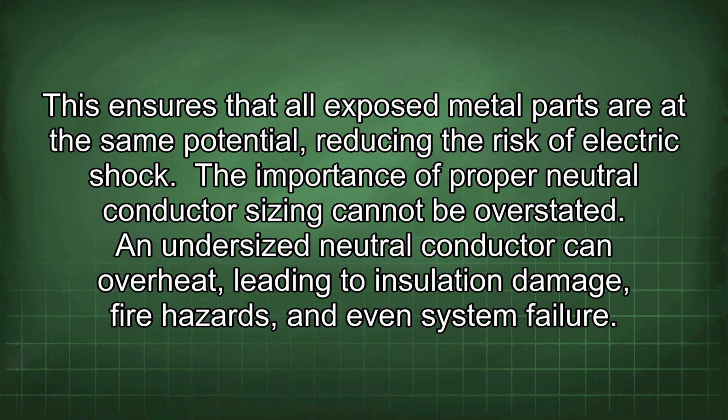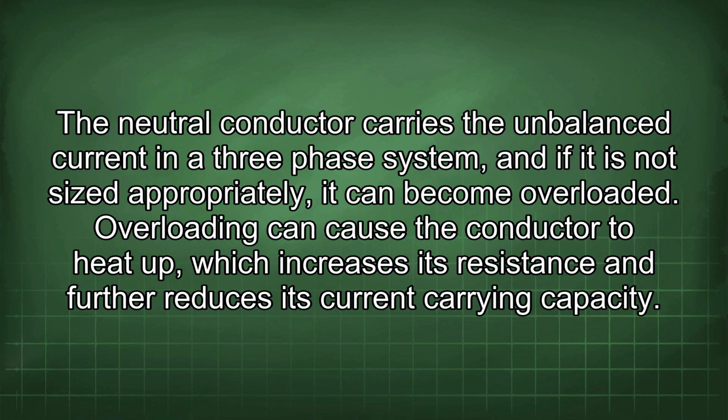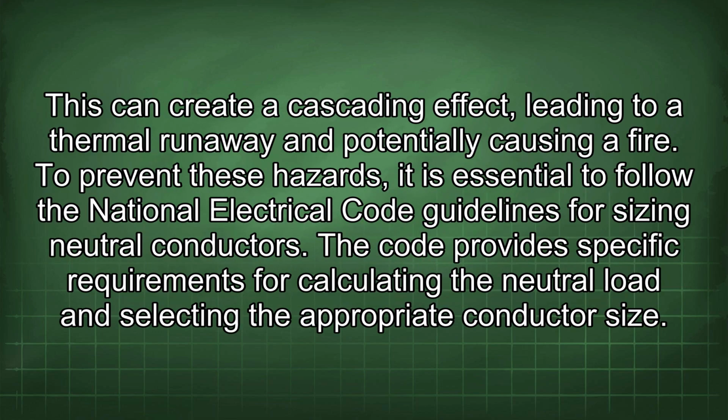The importance of proper neutral conductor sizing cannot be overstated. An undersized neutral conductor can overheat, leading to insulation damage, fire hazards, and even system failure. The neutral conductor carries the unbalanced current in a three-phase system, and if it is not sized appropriately, it can become overloaded. Overloading can cause the conductor to heat up, which increases its resistance and further reduces its current carrying capacity. This can create a cascading effect, leading to a thermal runaway and potentially causing a fire.